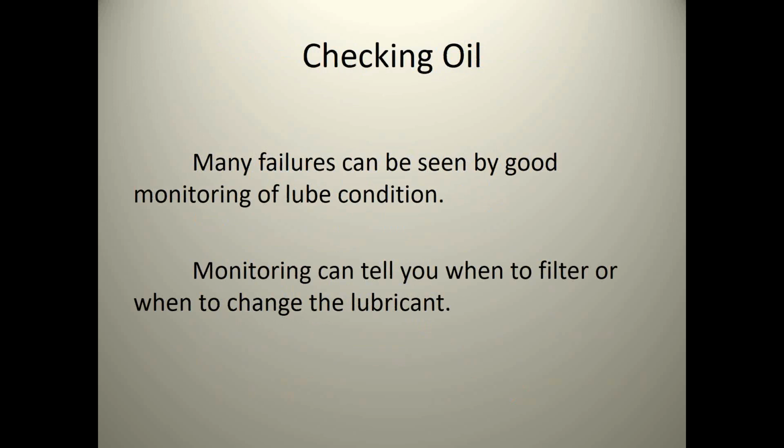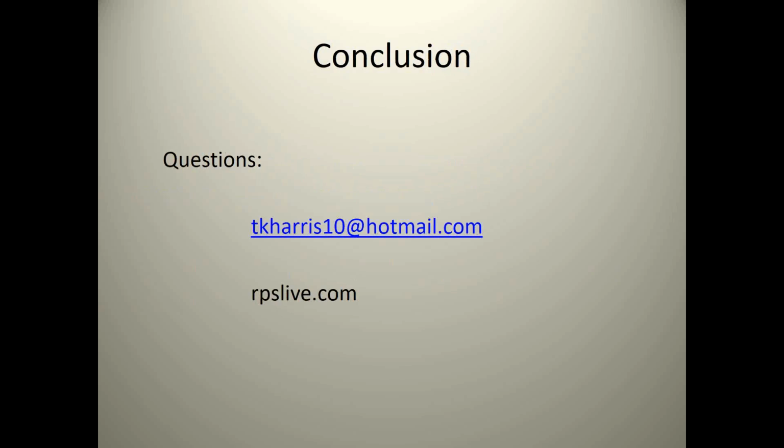Checking your oil: many failures can be seen with just a good monitoring program. So like I say, train your operators, start pulling samples, monitor the oil so you know when to change it. Lots of good practices around that. So that's the wrap up for today's session. We have a few minutes if there are any questions you want to type in. You have the email address here. If you've got questions you want to email, I'll get those answered right away. But I'm hoping you learned some things. Like I said, lubrication is at the top of our performance failure curve. If we get the lubrication process under control and get our lubes clean and dry, you'll start seeing longer life cycles of your equipment.